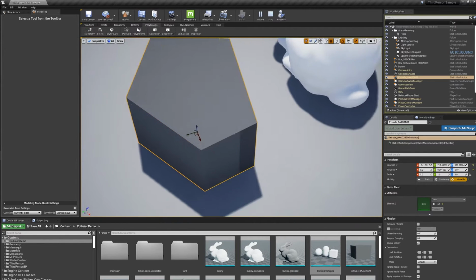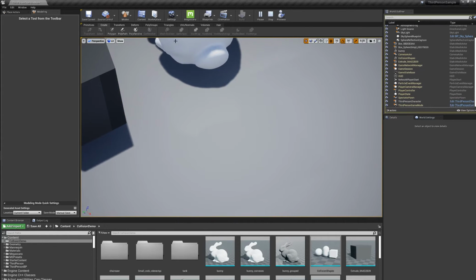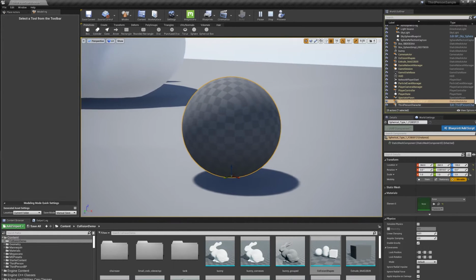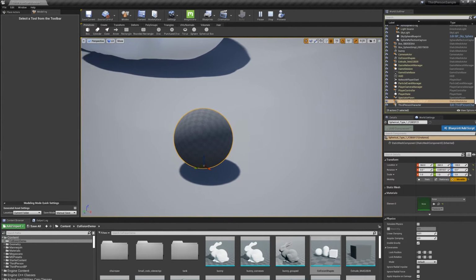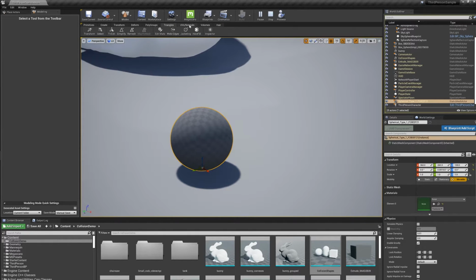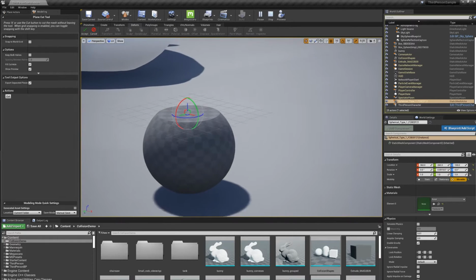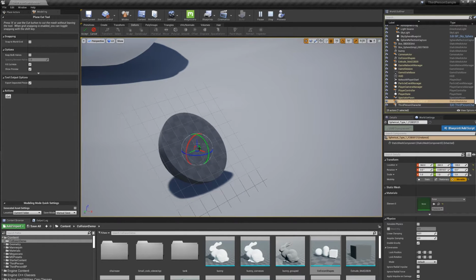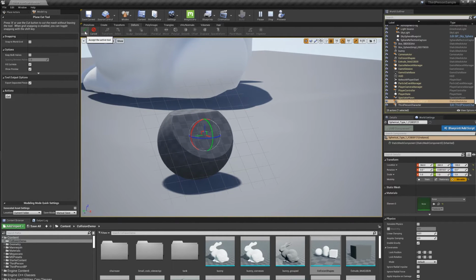And there's another way to explain this, which I'll do with a sphere. Oh, I made a sphere back here. I guess I kind of messed it up. Let's make a new one. Primitives. So another way to think about it, and this is useful to keep in mind as you're trying to figure out how to approximate your shape with convexes, which is what a lot of this tutorial is going to be about, which is why I'm spending so much time explaining this, is if you take your sphere here and cut it with planes. As long as we are just applying plane cuts to this sphere, it's always going to stay convex because the initial sphere was convex, and all the plane cuts can't change the convexity, as long as it's a whole plane. The shape will stay convex.